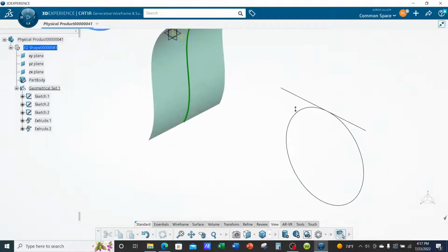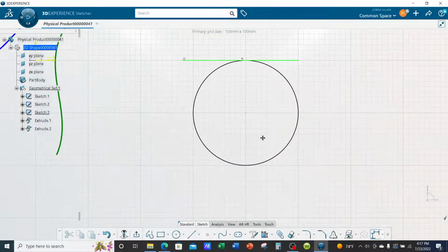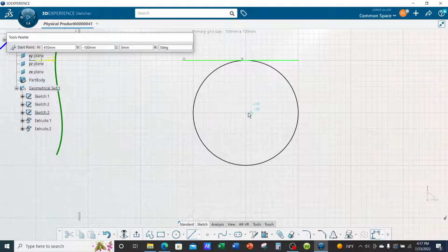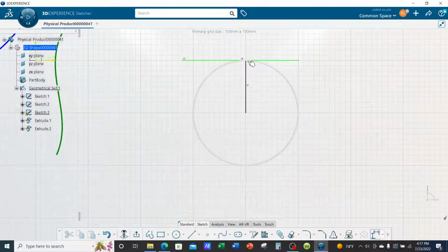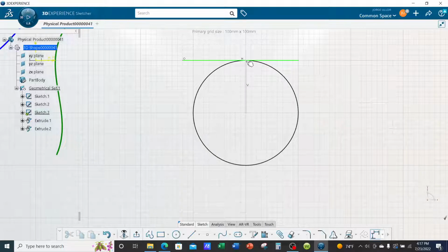Just like the sketch on the circle, we have the line perpendicular to the curve, where we go from the extremum vertical point, or I should say the top quadrant point on the circle, to the center, right? And they both come off at 90-degree angles. So there we have tangency. So we're trying to accomplish tangency just like the line to the circle, intersecting at one point, point continuity, and it's also tangent. So it's C0 and C1. Okay, I'll exit this sketch.